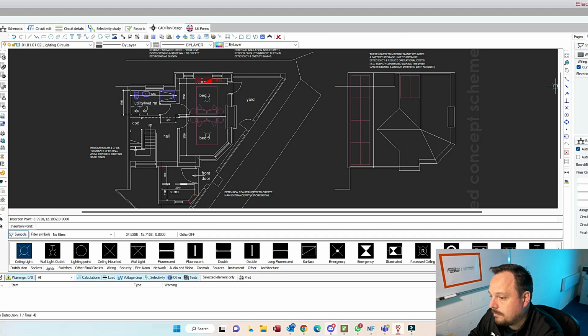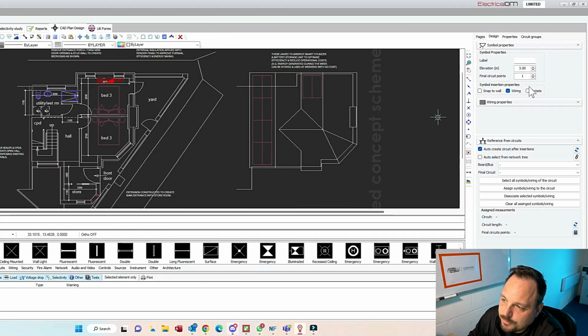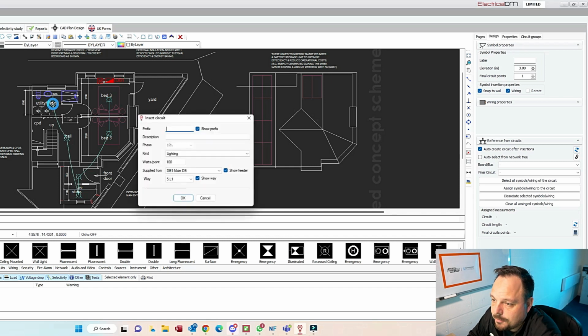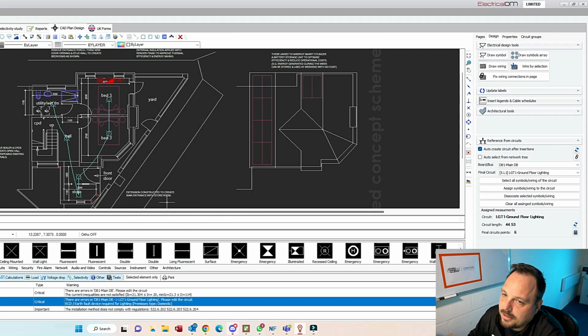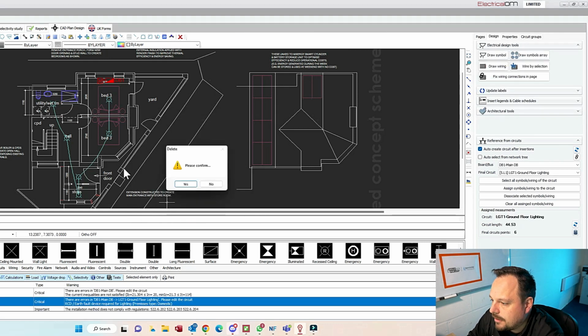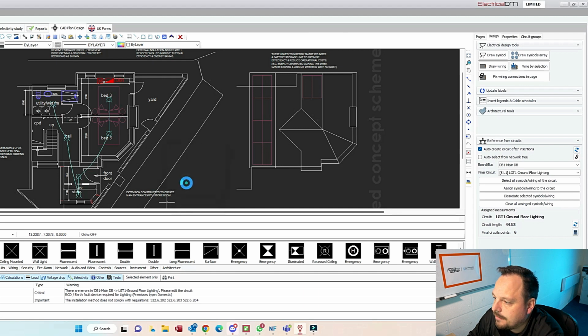And you can see with this first drop, I've made a mistake. I forgot to tick the wiring link between those points. So I need to make sure we tick that box and snap to wall. And we're going to run through and drop the pendants in each room. There's no snazzy spotlights or anything going on in here. It is just basic central light fittings. And again, you can define that when you right click away to say you're finished, that this will auto populate onto the circuit details, ready for you to make those adjustments in the circuit edit feature.